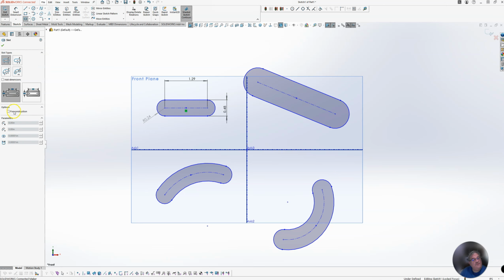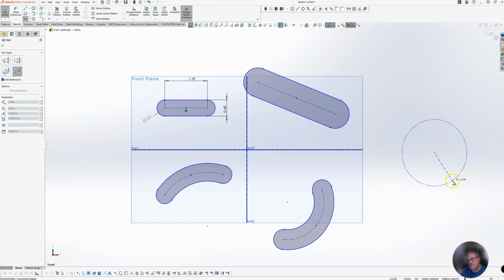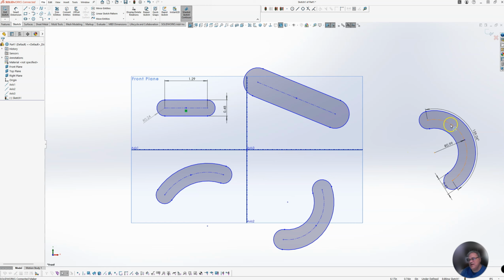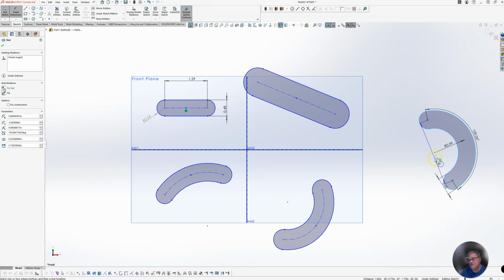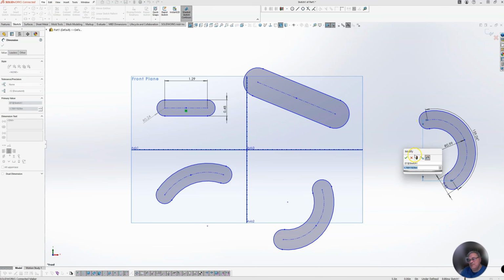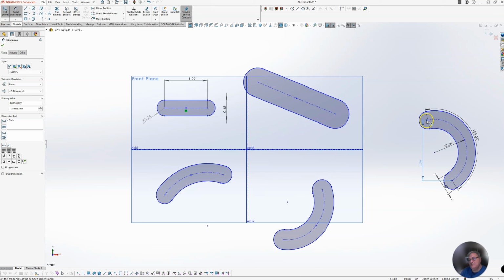Then if you want, you can hit add dimensions. So let's do that last one again. So you're going to do that, pick your arc, and then there you go, it's dimensioned. This can bite you in the rear end, and it can make your life easier all in the same breath, because now you're constrained. You might forget, and you add a dimension to it saying, hey, I want to know the endpoints. So that one's going to work just because of the way it is.